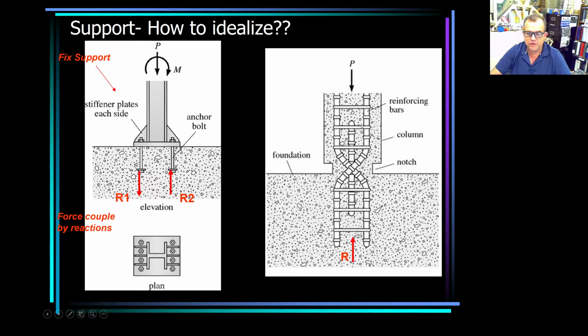It's the same situation because everything crosses at one point, meaning in this direction it's not going to move and in this direction it's not going to move. However, if I apply a lateral force here on top, this is going to be able to rotate, meaning this support here will be a pin support. Don't be too worried about that. I'm just telling you this for engineering purposes.